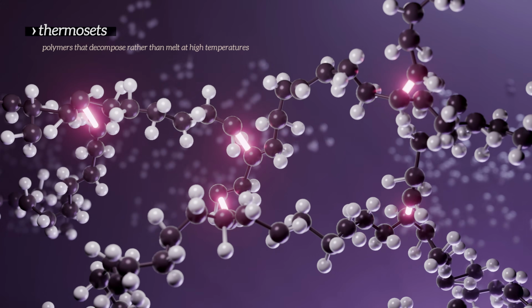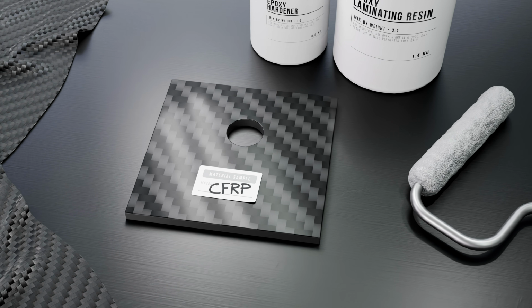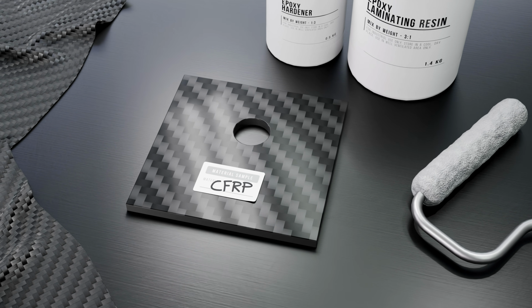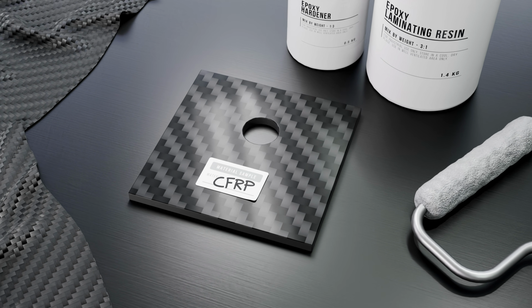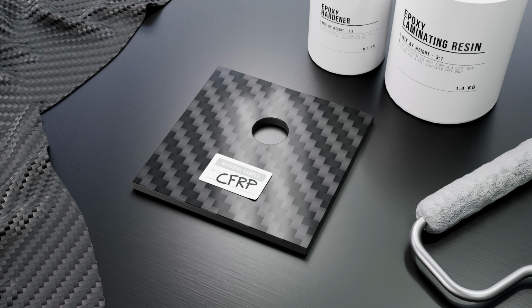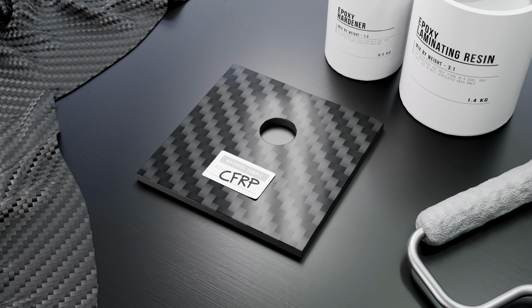They're commonly used in adhesives and in composites, like the epoxy resins in carbon fiber reinforced polymers. Thermosets often start as prepolymers, liquid resins that contain partially polymerized chains. They're transformed into a rigid material through a curing process, where heat or a catalyst are applied, triggering chemical reactions that form the cross-links between polymer chains.